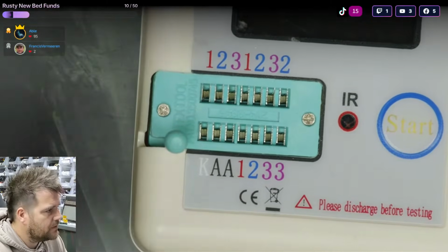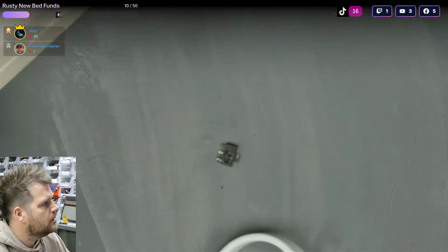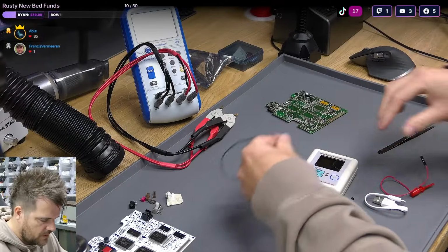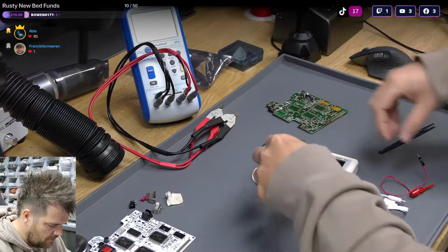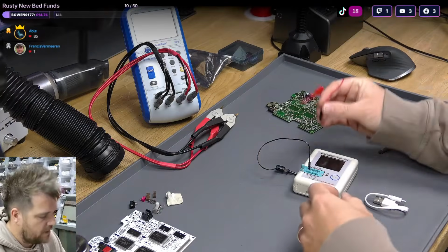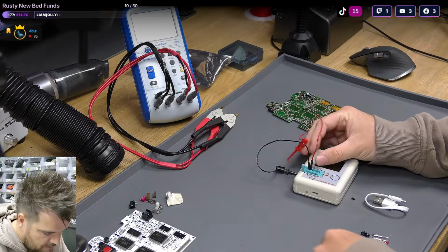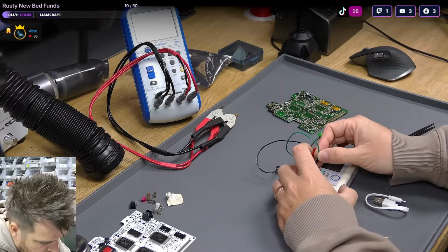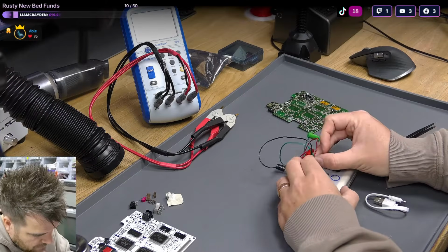A and K is anode and cathode for testing diodes. So basically we're just going to put the 3 leads in, 1, 2 and 3, and then remember the order, because when it figures out what components are, it shows up on screen and says pin 1 is this, pin 2 is this, pin 3 is this. So that's the only relevance. You can put them in any order, but it'll tell you on screen what the pins are.